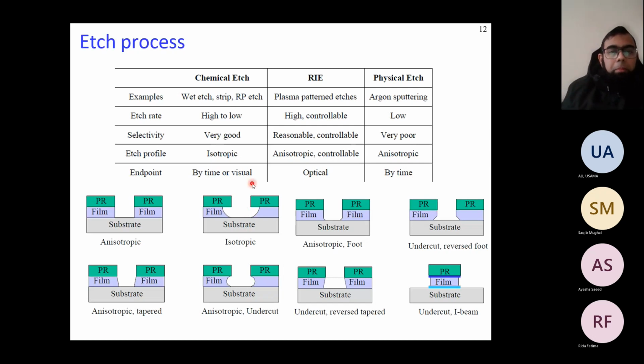There are multiple ways of etching, like dry etch. Dry etch is based on plasma etching. You bombard with argon plasma, or maybe another kind of plasma, I think inert helium plasma is also being used. You just sputter, like firing balls on any surface, and it etches. It's also a very costly process, but it's anisotropic. That means it etches in a single direction.